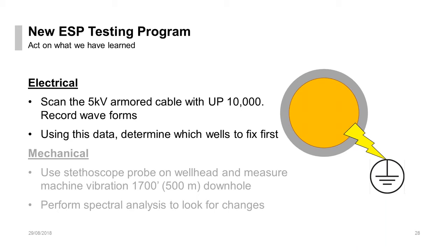to ground. And as most of us know with our ultrasound training and background, when you have arcing, an electrical phenomenon, it causes ionization of the gas, and that's what we actually hear, the turbulence caused by that ionization. So in this particular case, we were listening to the leakage, finding a path to ground, and ionizing some gas along the way. And that's what that little graphic on the right is indicating.